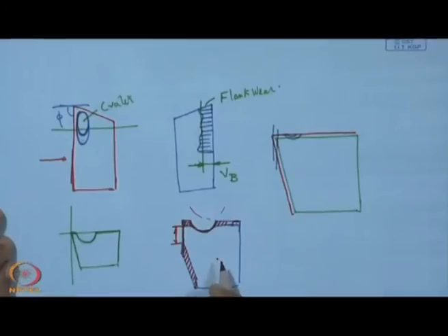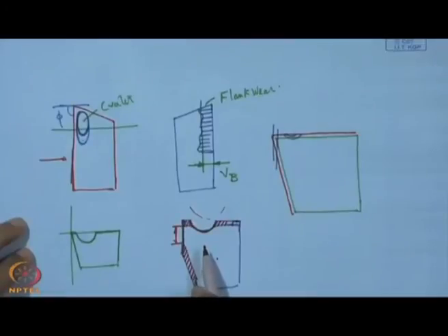Because of the high wear rate as the tool moves along the axis of the job, there could be a shortfall in the depth of cut, which may lead to taper turning. So, if we have a proper coating like titanium nitride, that can also be useful in holding the accuracy of the job.